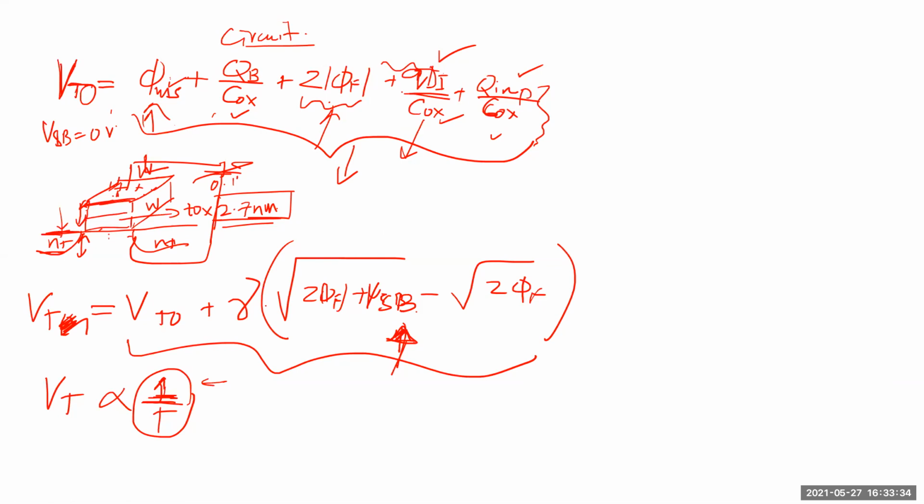Is this clear? I think a lot of people, I think Somi also got that in the beginning, that you can control it. So the only control, like I said, is VT. So VT is really a process parameter given to you as a designer. Looks like a lot of you didn't have that clarity. As a circuit designer, you can't touch any of these. They're all fixed. Makes sense? Any questions?